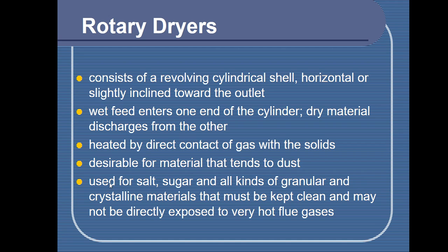So, if the drum dryer cannot process salt, although they are the same in terms of physical design, the rotary dryer can. So focus on each dryer in terms of what feed it can handle, and most especially on the type of drying method that is being used.